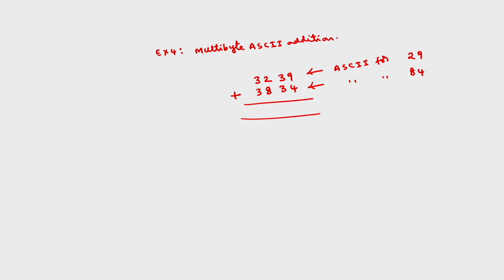As I already discussed while covering the ASCII instructions, 0 is nothing but 30H. If I press the 0 key on an ASCII keyboard, internally 30H will be generated. Simply add 30 to that key: 1 means 31, 2 means 32, and so on up to 9 means 39.